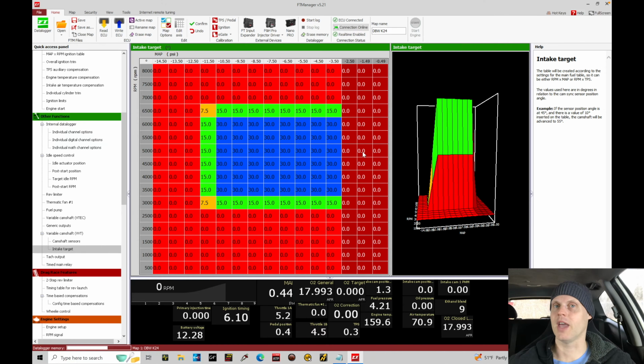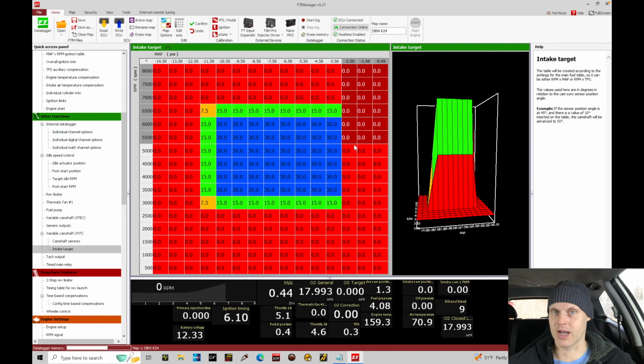We'll probably find that the engine doesn't respond very well to high cam targets here, or a lot of overlap at high engine speeds. So we're going to learn how we can dial this in and actually build a proper cam composite blend, not only using the Mainline dyno to see the before and after as we're changing things, but taking a look at our log data if you don't have a chassis dyno to do your tuning process.